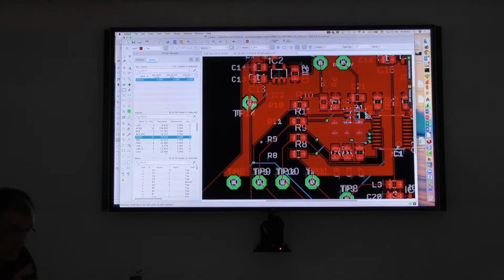There are different settings, different modes for the polygon, where I can also say, okay, fill areas, so-called orphans, inside my contour that are not connected to DGND. Sometimes it makes sense, in most cases I think I wouldn't do it, it depends on the design.